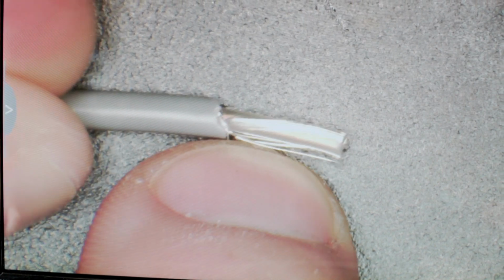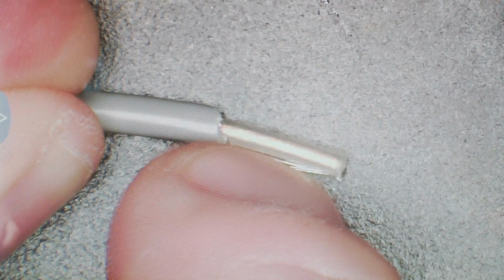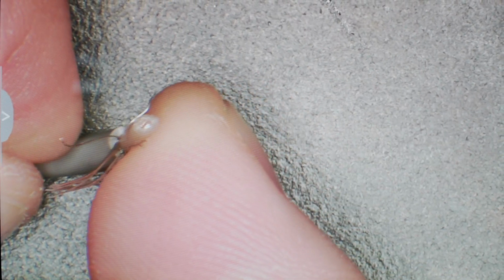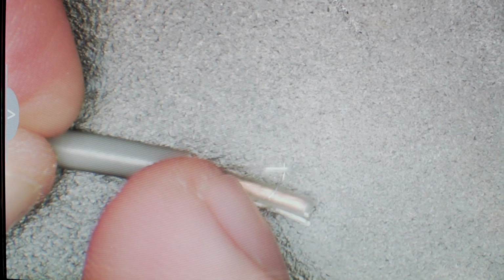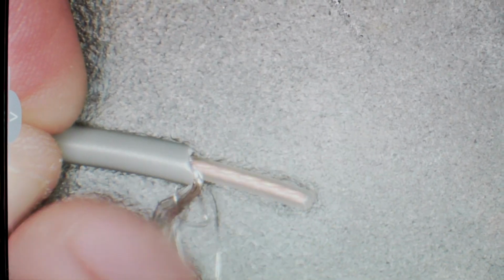So the shielding for this cable, if you look in here, you can see that the cable has the metal insulation there. That's what we use for the antenna. It does have the center conductor wrapped in that plastic protective sheathing. That's what actually carries the signal. So during the process, we're going to trim away the antenna portion, which we're not concerned with, and we're going to focus in on the signal portion.